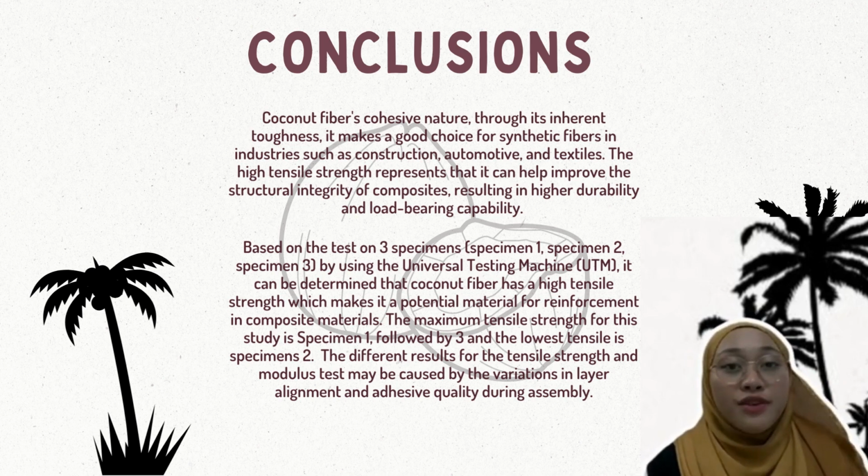The maximum tensile strength in the studies is specimen 1, followed by specimen 3, and the lowest tensile strength is specimen 2. The different results for the tensile strength and modulus can be caused by variation in layer alignment and adhesive quality during assembly.